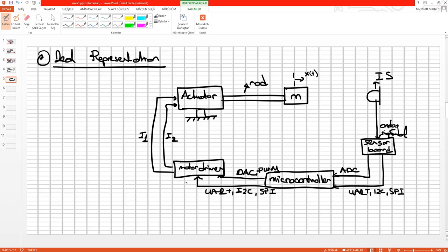So this motor driver is given in here, and then we also have a power supplier in here, right? This should be fed with 220 volt AC, and then maybe in your case the motor driver should be fed with 24 volts, okay?